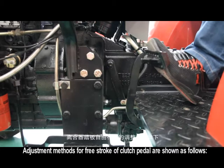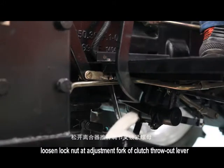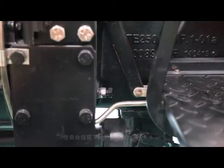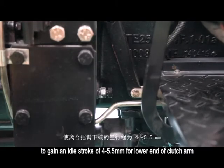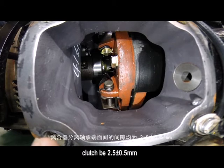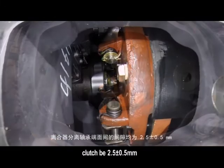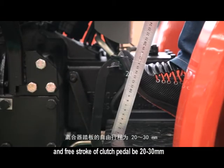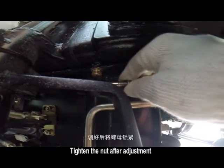Adjustment methods for free stroke of the clutch pedal are shown as follows. Loosen the lock nut at the adjustment fork of the clutch throwout lever. Rotate the fork to gain an idle stroke of 4 to 5.5 mm for the lower end of the clutch arm. Ensure the clearance between the working face of the release lever and the face of the release bearing of the main clutch is 2.5 ± 0.5 mm, and free stroke of the clutch pedal is 20 to 30 mm. Tighten the nut after adjustment.